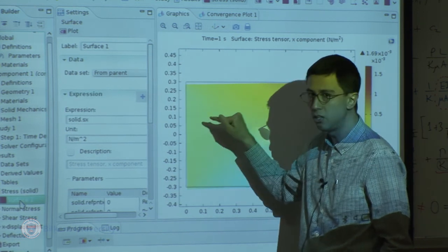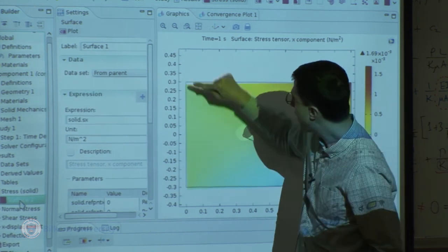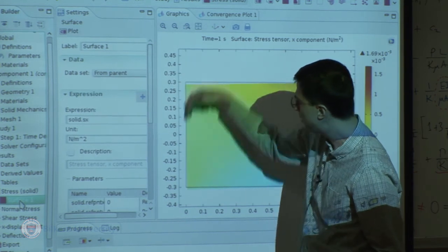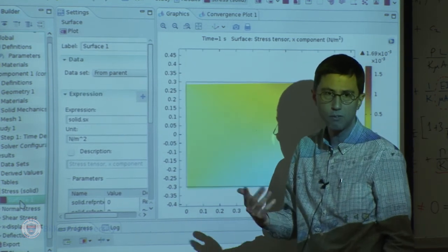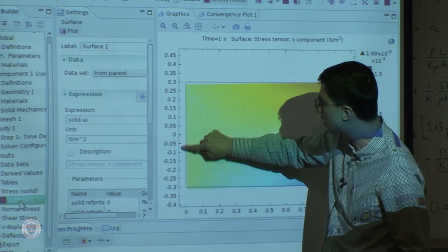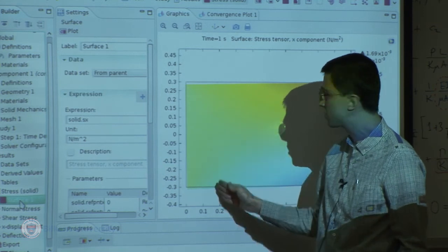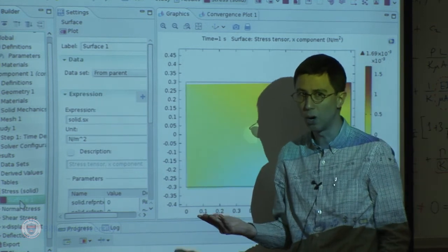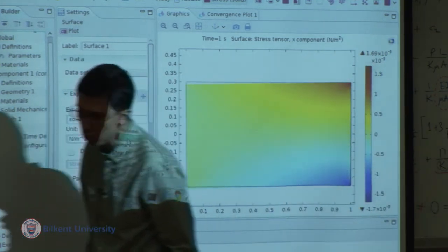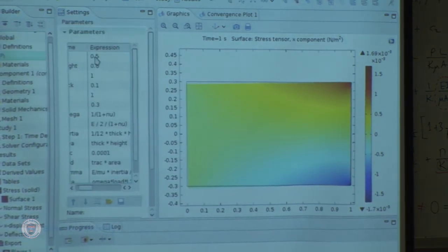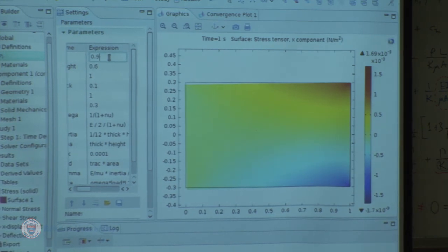So presently, the numerical solution takes a constant shear stress distribution such that it integrates to a net force, a given force. Okay, so shear stress is a constant along this end. I know that my shear stress here, for instance, is VQ over IT. It's parabolic, so it will be a mismatch. It will introduce an end effect. So let's look at those. So first, instead of 0.5, I'm going to choose 0.9.